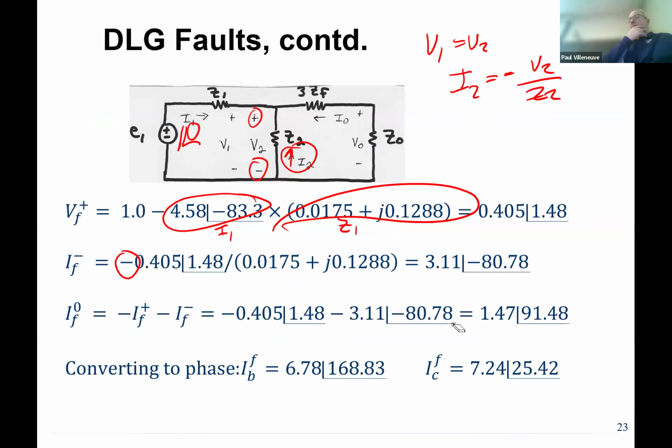So in the real world, if you didn't know what the fault was, would you do all three, or would you try to find out what the fault is? It depends on what you're trying to do. If you're trying to determine what the fault current settings would be for a relay, you would most likely run the three-phase fault. That tends to be the highest. And normally ground fault current is so low you don't have to run it, but as a backup you could do all three of them, because it's usually just an option you can click. It's pretty easy to go ahead and do these.